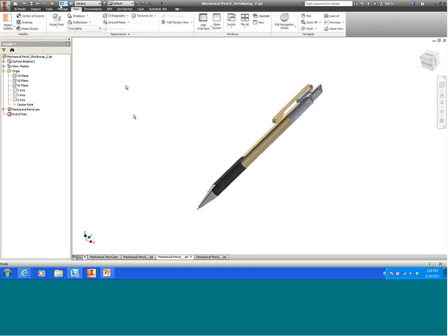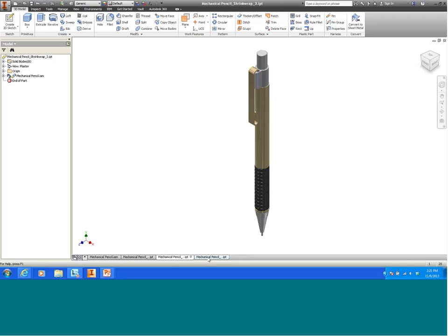The same thing in my surface model. I can pick my update, and the clip has also enlarged, so it's recognized the change. Now this final one, this was the multi-body that I disabled the associativity on. You can see in the quick access that that update is not available. So the link between the two has been killed. There's no associativity at all.